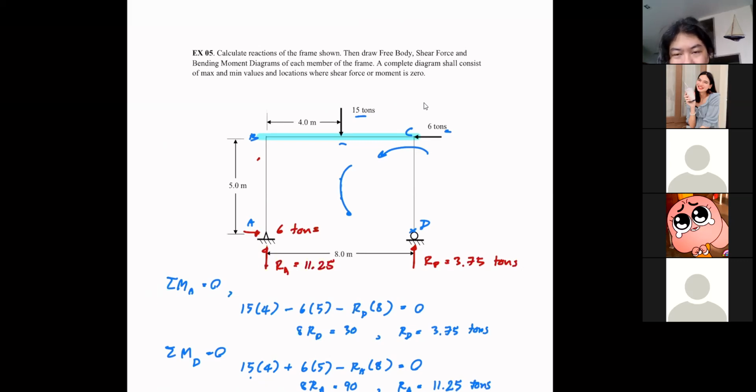You can make the steel like 20 meters long, but how are you going to transport it? So generally, the typical widely accepted length of one member is 6 meters. So if you are going to construct this, it means that you need 2 pieces, correct? So when you need 2 pieces, you need to make a connection somewhere.